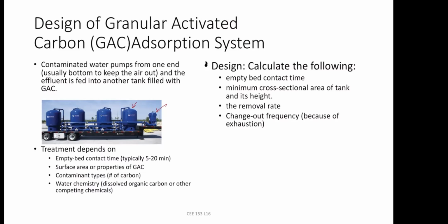Empty bed contact time means how long it takes for the water to move through the activated carbon tank, through those pores. Usually it should be 5 to 20 minutes, because you want to treat a lot of water. And the activated carbon surface area has to be very high, because the adsorption depends on the sticking on the surface. So the more the surface, the more the removal. So that means if you make the particle size smaller, it has more surface area.